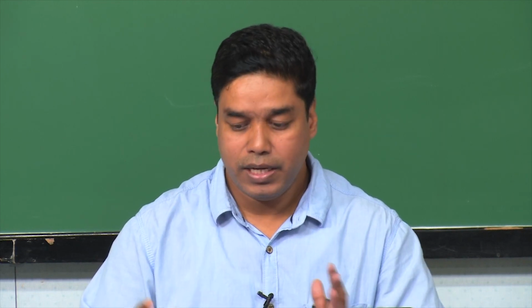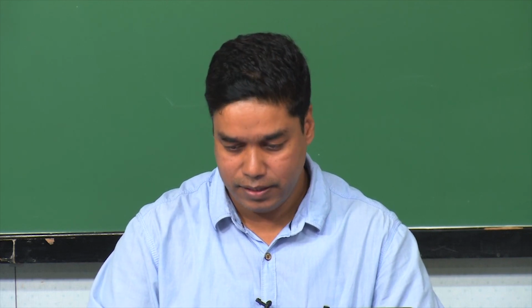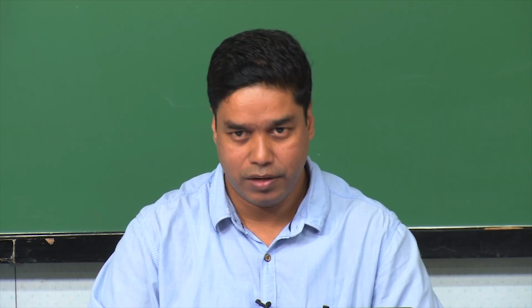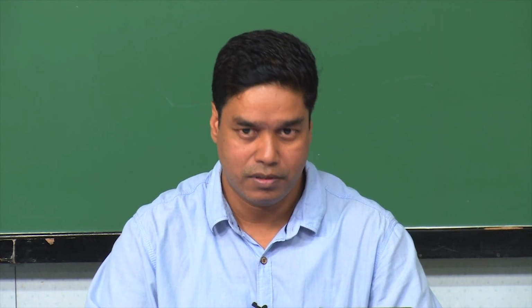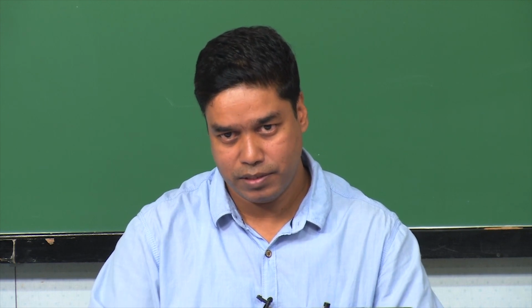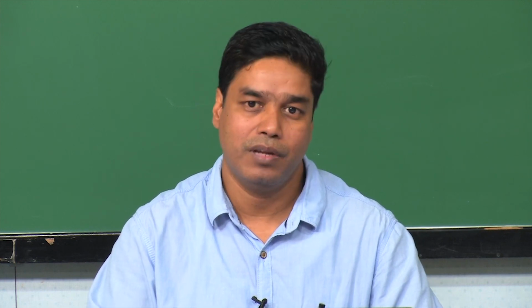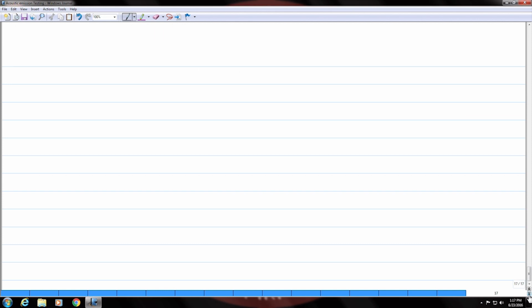Okay. So, that is why there is a previous load history that also has to be considered when you talk about acoustic emission events from a part when you are doing the inspection at particular intervals. Okay. So, these Kaiser and Felicity effects will tell you about that, and this is how they go.